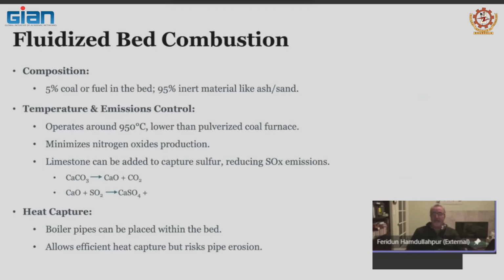Why is the temperature an issue? If the temperature is above a certain level here, you basically bake the calcium oxide particles, and then you don't get the benefit of the porous structure. It's like you bake it. It's just the surface that is in contact.